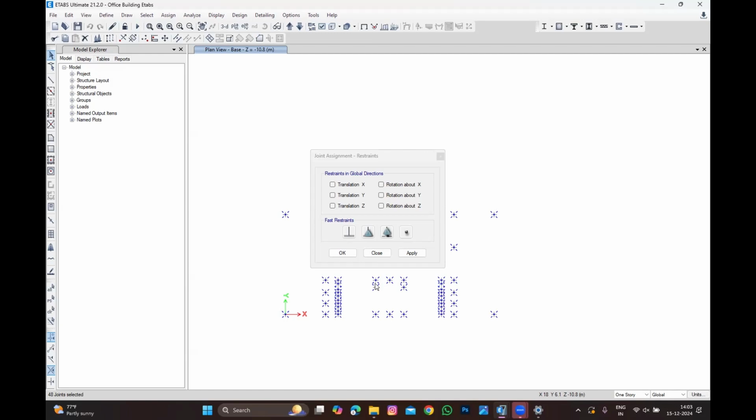That is the reason you will have a massive depth. It's not because of the vertical force. For the vertical force, it might require only 700, 750. But when you're going for the moment, it requires 1.2, 1.4, 1.5 meters. That's the reason the crane foundation is always not less than 1.4. It will pass at 1.2, 1.3, but due to the crane constraints, we need to embed one mast downward, like half of the mast. And to support half of the mast, I need the leg. The leg needs to be 700 to 750 millimeters. You get my point. So it is almost 1.4 to 1.5 meters that we need to go for.